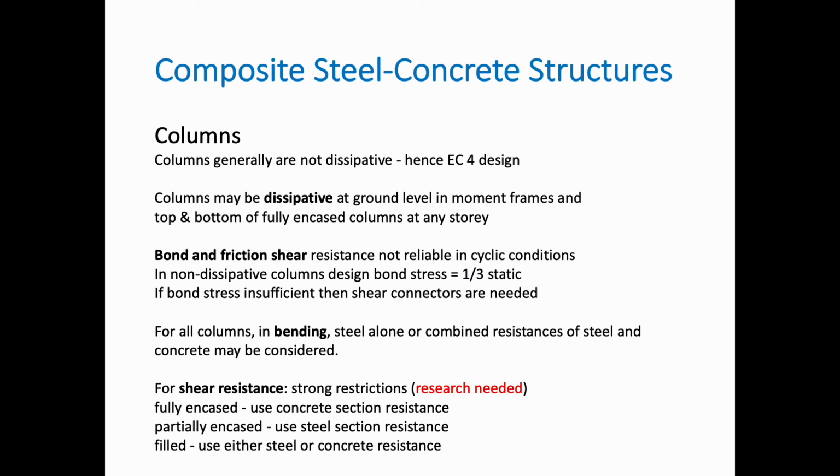Looking at the composite columns, generally these are considered as non-dissipative structural members, therefore we use Eurocode 4 to design them. Columns may be dissipative at ground level in moment frames, and at the top and bottom of fully encased columns at any story.